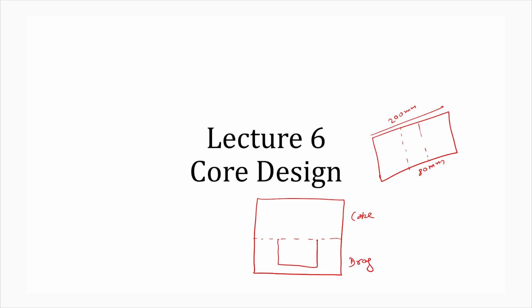How can we create a hollow product? I can place one additional feature of the required size. It is made of sand, similar to the mold, but the strength can be different, and it will be placed inside the cavity.